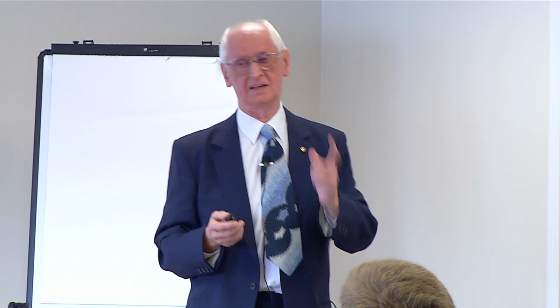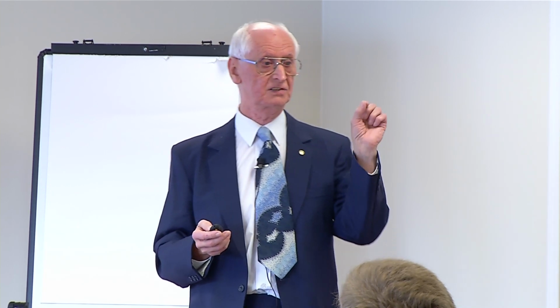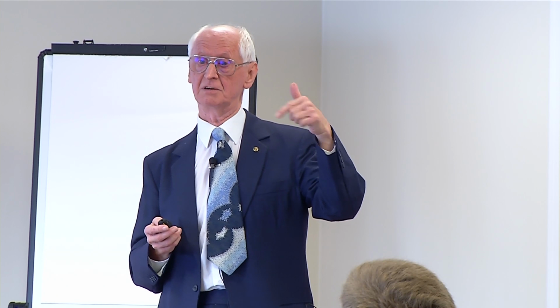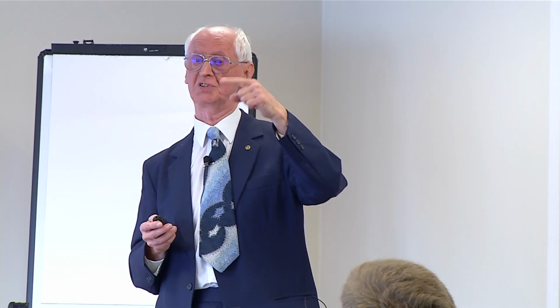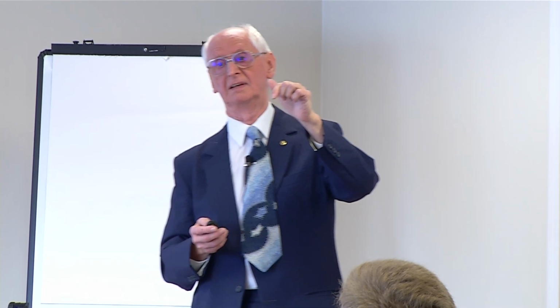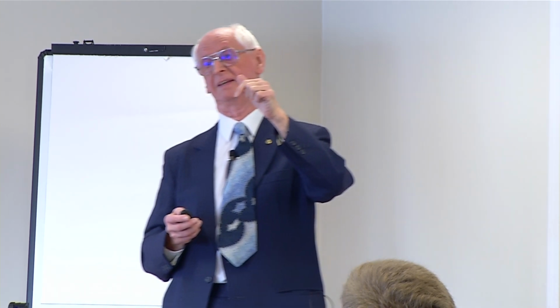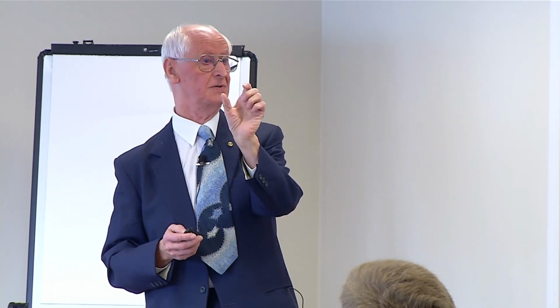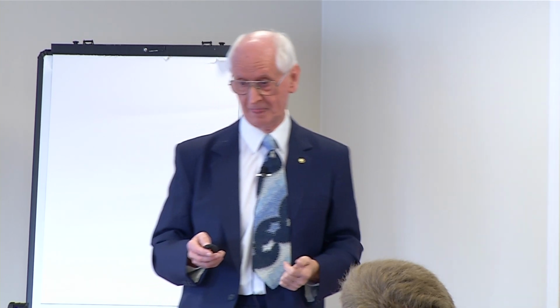But the reason it came off was this bimetallic corrosion between the stainless self-drilling screw and the aluminium. Where they drilled through the sheeting, the aluminium and the stainless were in such close proximity that with a little bit of rainwater, it just corroded around the head. The fixing was still there, but the sheet had come off.